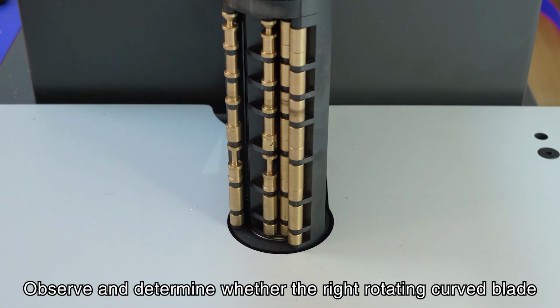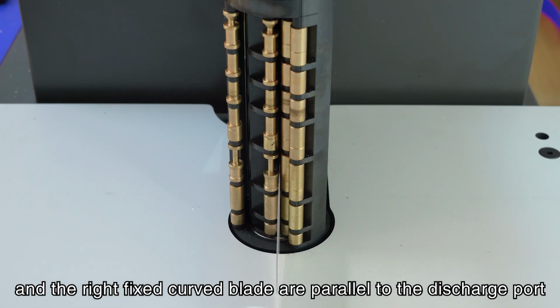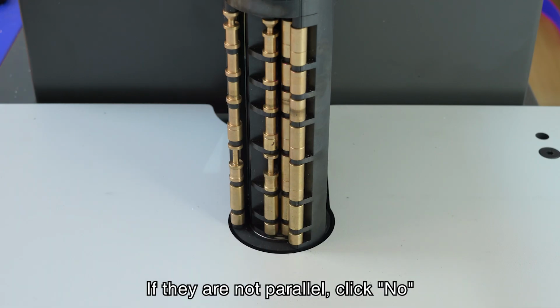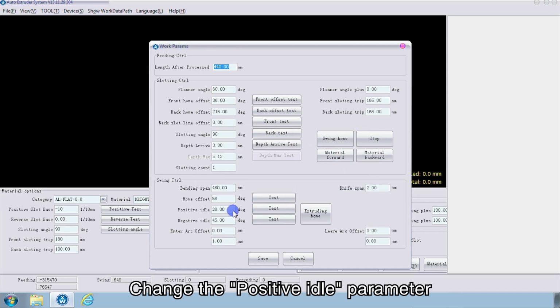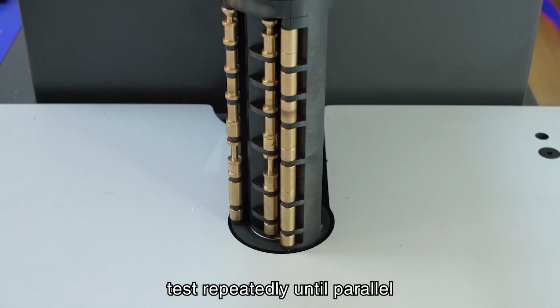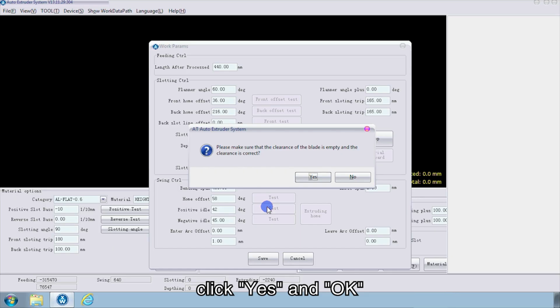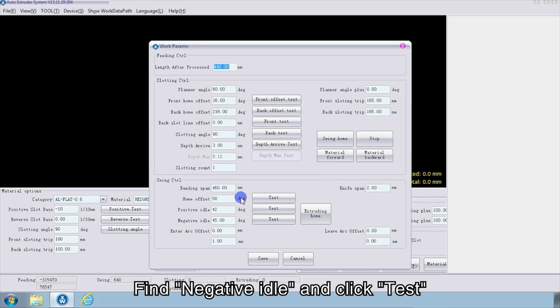Observe and determine whether the right rotating curved blade and the right fixed curved blade are parallel to the discharge port. If they are not parallel, click no. Change the positive idle parameter, test repeatedly until parallel. Click yes and OK. Find negative idle and click test.